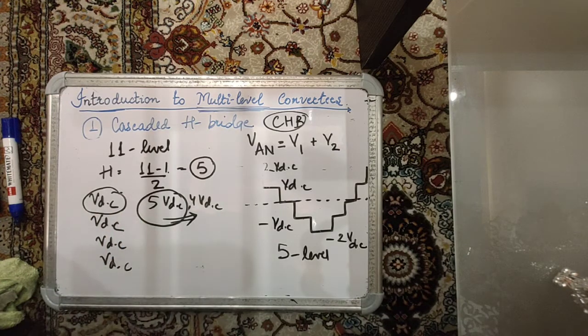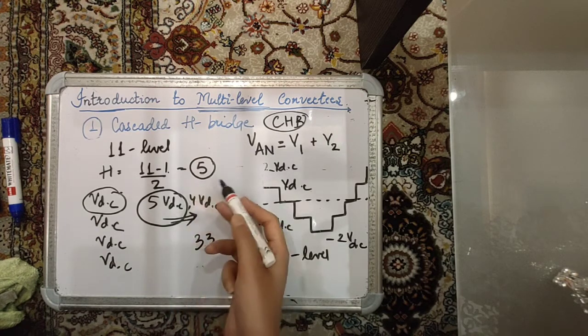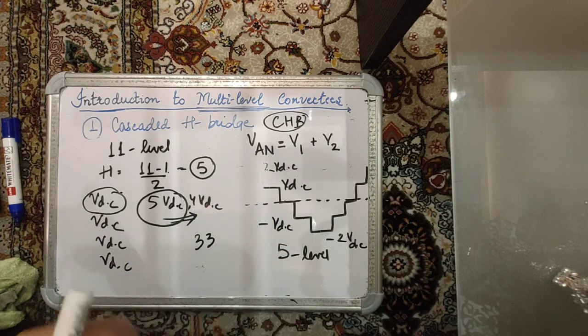This is another beneficial thing in high power converters, not just that your power losses are minimized through multi-level converters, but also in high power applications where it is likely that your converter might be operating at say 11 kV or say 33 kV. Then even if your AC voltage is 33 kV, each switch, if you are using a very high number of levels, may be rated at a much smaller value, say around 33 kV by 5 if it's an 11 level converter. If it is a 5 level converter, then it will be only halved.